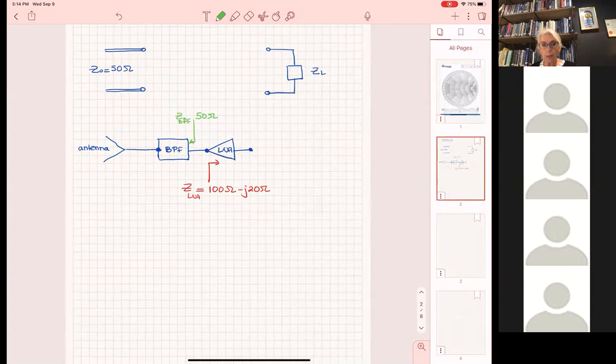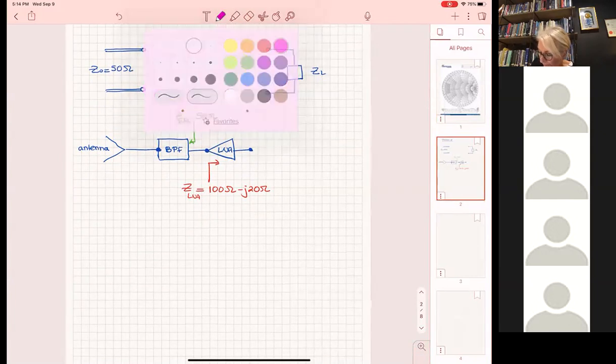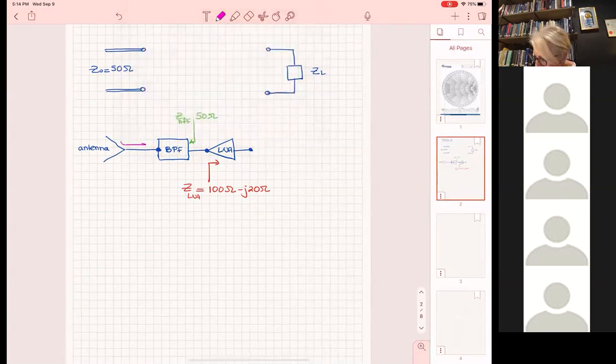So then they say you have to put them together in the system. So how would you do that? You will have to put at the center, in between the two, a matching network. Otherwise, when the power comes in from your antenna to your filter, and if my filter design is good and goes through the filter and is filtering it, but I'm not losing a lot of power, then when the power comes out from your bandpass filter and sees other than 50 ohms, part of the power is going to go back.